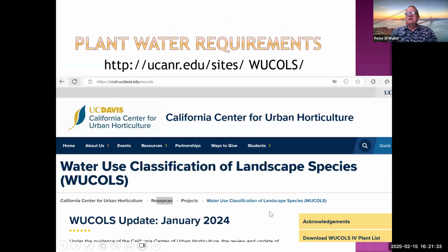Okay, let's move on to plant water requirements. So as you can imagine, with 3,000 different potential types of landscape plants, it's rather difficult to obtain a crop coefficient for each. But Costello and Jones in 2014 in California organized some committees of landscape architects and they assigned crop coefficients, or what are called landscape coefficients, to all the types of plants that were used in California.